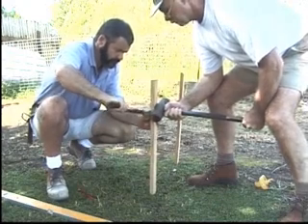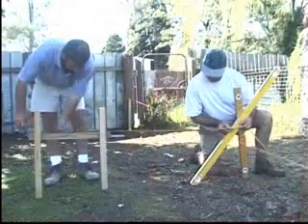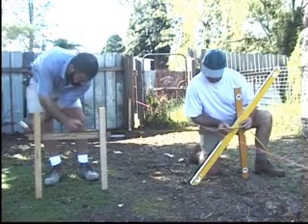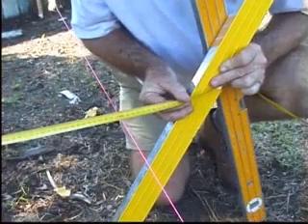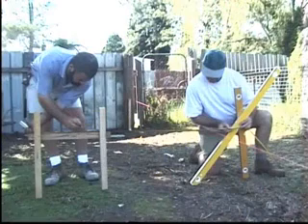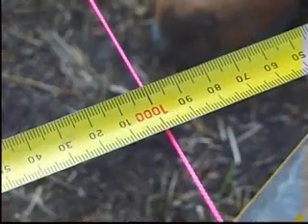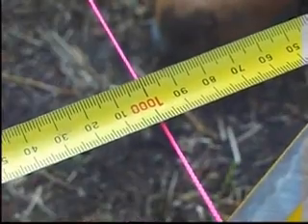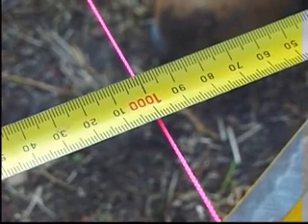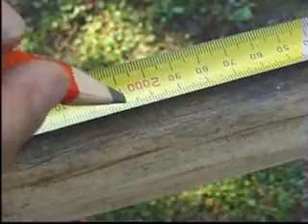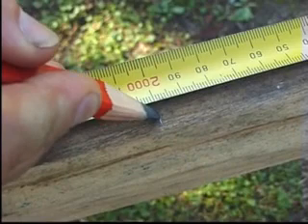The side setback distance indicated on the site plan is measured square off the side boundary string line to each of the 2 profiles. Greater accuracy is achieved by measuring from the metre mark rather than the end of the tape and then adding 1 metre to the final measurement.